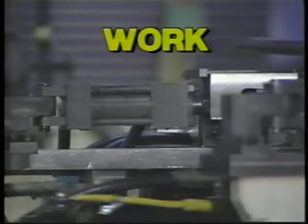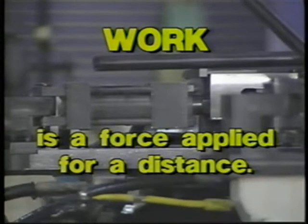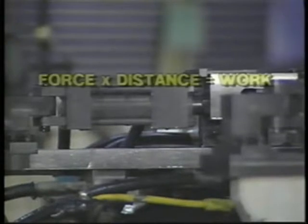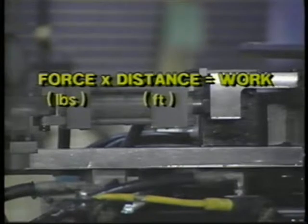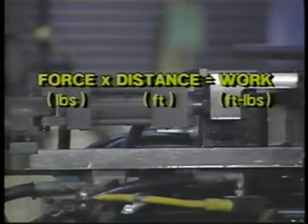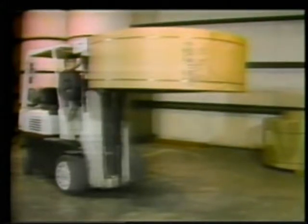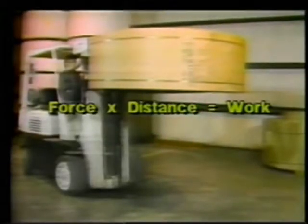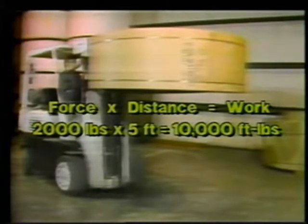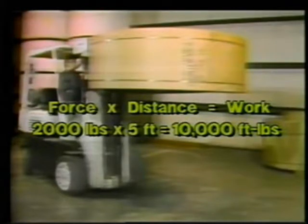But what do we mean by work? Well, by definition, work is a force that is applied for a distance. Written out in equation form, it looks like this: force in pounds times distance in feet equals work measured in foot-pounds. Let's take a look at the work this forklift is performing. If the forklift exerts a force of 2,000 pounds over a distance of 5 feet, then, according to our equation, we have 2,000 pounds of force times a distance of 5 feet equals 10,000 foot-pounds of work.